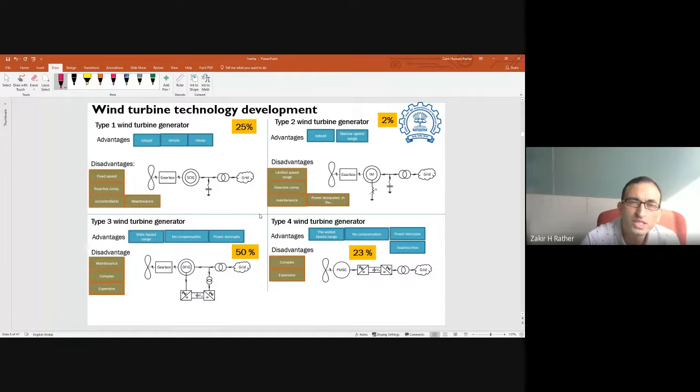You are going to displace those sources either temporarily or permanently. By temporarily I mean the diesel generator or synchronous generator is still there in the system, but because you have a decent amount of renewable, you will be tapping the generation from renewable. So what does that result in? You will not commit the conventional source.